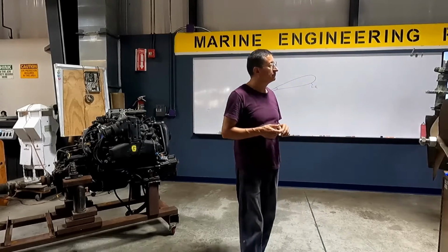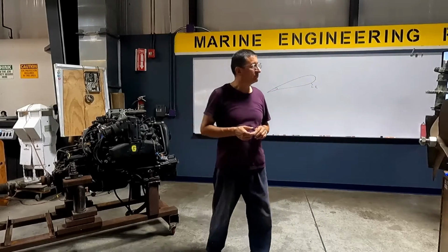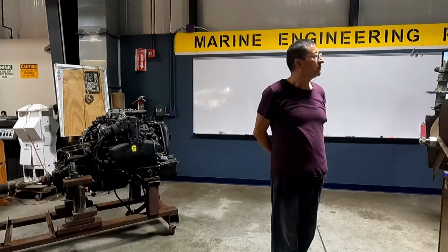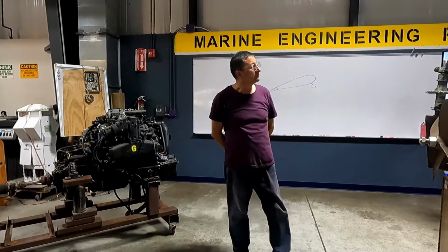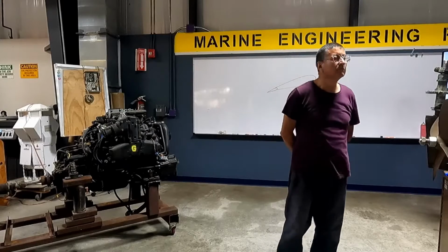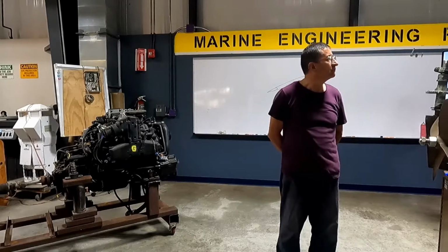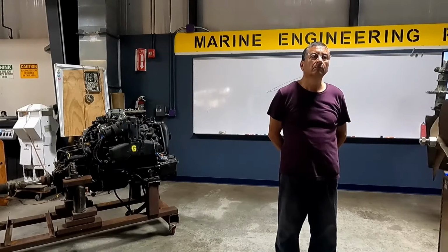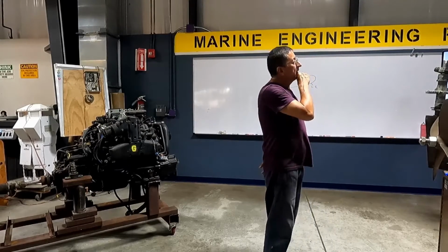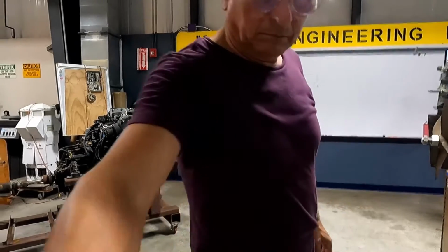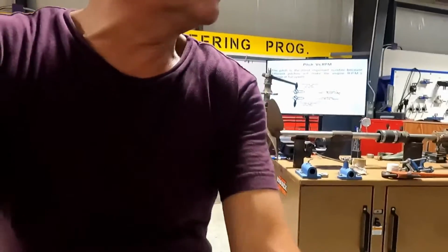Now, just talking about the pitch, you have props that are, you remember the cup? You can modify the props the same. Like you have, let's say I have this prop and it's a 17 pitch. It'll stay at 17 pitch, but you can cup it, change the edges a little bit. You can modify it. That's for the guy who's really into the high performance. Joe Schmo is just going out there going fishing. He doesn't care if it's going fast. But I mean, I have some customers that I have to give like 10 different props because he's just looking and tweaking it and it's okay.